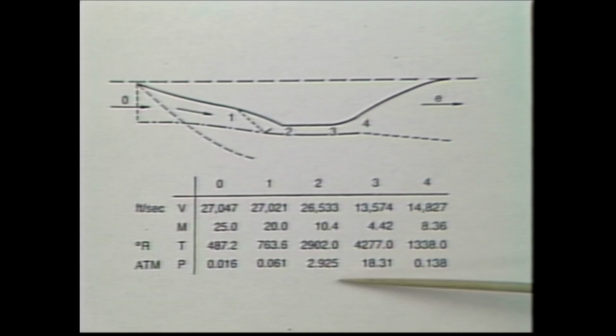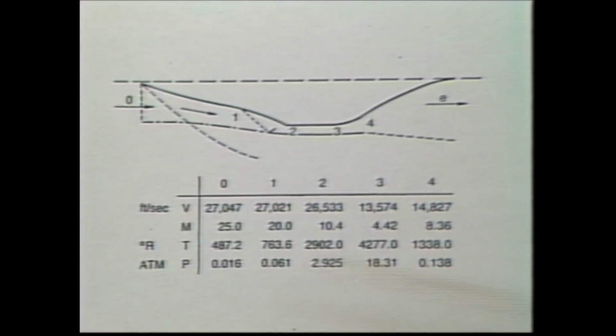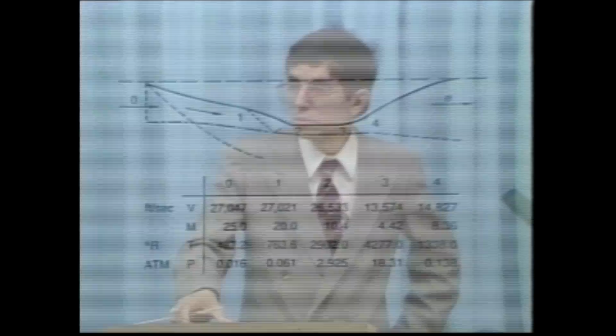This is something that we'll be talking about later. We'll see that for the combustion system, you really have to provide pressures on the order of about an atmosphere, or at least a substantial fraction of an atmosphere, if you want the combustion system to proceed to completion in a reasonable length engine. Question in the back?